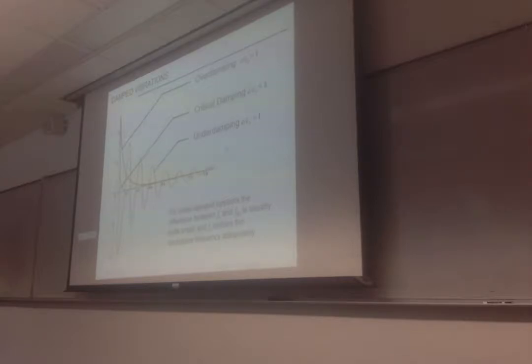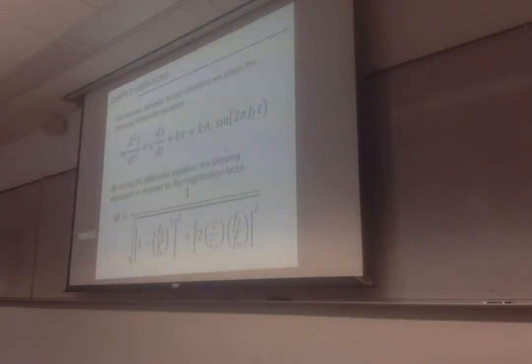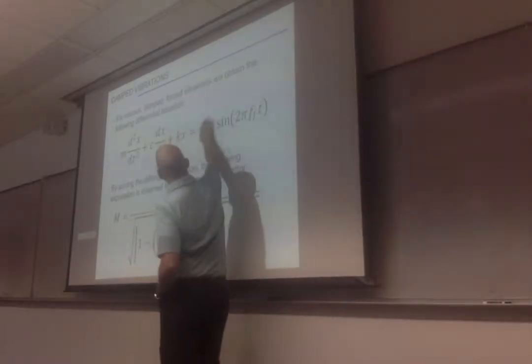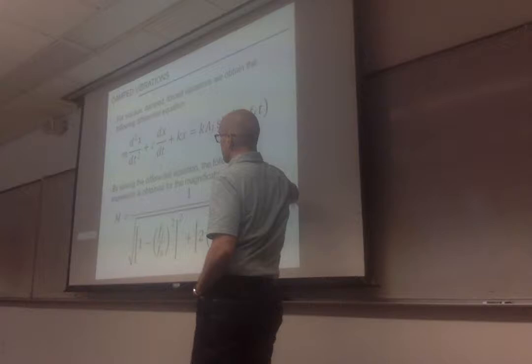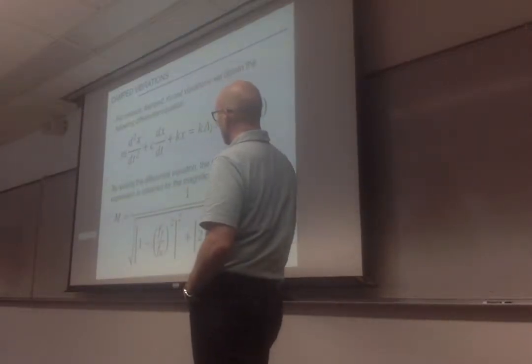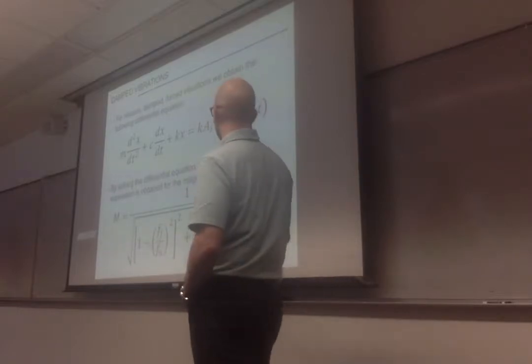And it also means that the natural frequency for packaging applications usually defines the resonance frequency pretty well. So if you go to the next step, as we've done in the past, we go from free vibration, where we introduce the natural frequency, and we look at what happens with forced frequency. It's the same equation, but you have a source term on the right-hand side that is actually creating the motion. It's not just set into motion and left to go back to equilibrium, it's actively shaken.